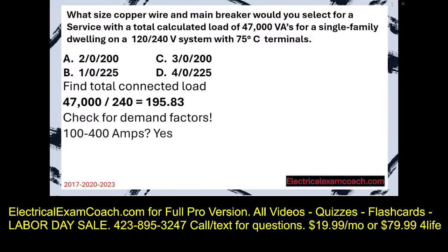And in this case, we do have a demand factor. Is this in between 1 and 400 amps? Yes. Is this on a single family dwelling? Yes. So the 83% rule does apply. So we get to use the table.